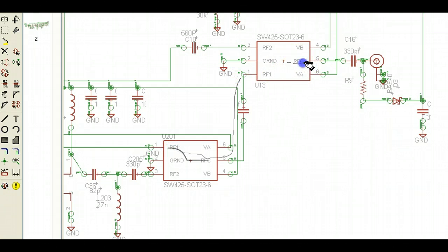It's this way, and this is the final transmit receive switch. Energy flows to the antenna port. If you take this route, the output at this point right here is about 300 milliwatts, and that's enough power to close the link. So the two signals we've talked about so far are the transmit enable, the push to talk, and the audio.